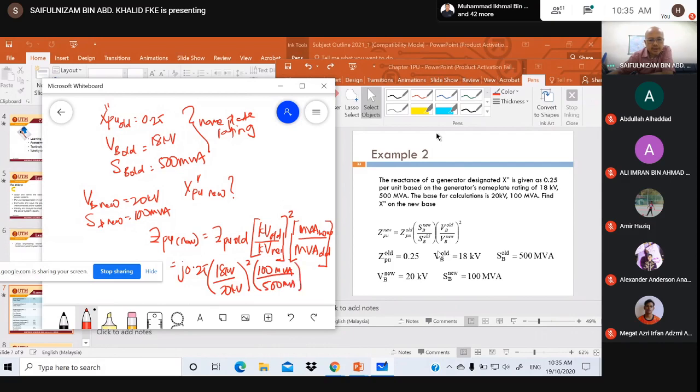So what do you get? What is the new per unit value of the impedance based on the selected base kV and MVA? 0.0405 PU. Don't forget j, put j here.